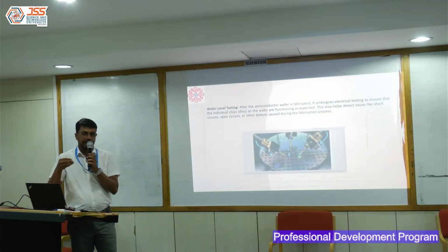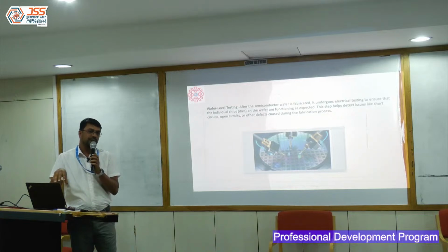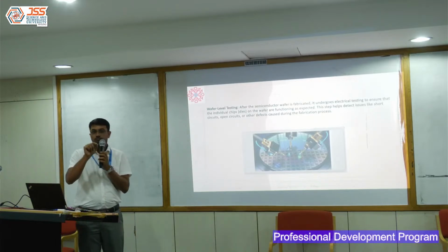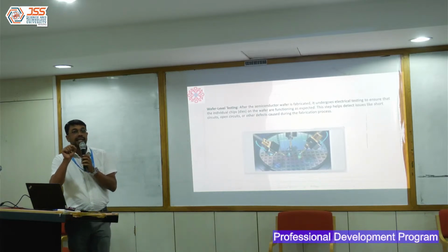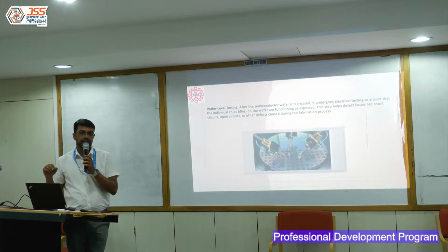When this technology started as a new technology, the yields were typically 20 to 30%. But they also learn from the first set of fabrications that they do. As I told you, I was talking about something called yield analysis. When I said yield is say 20%, out of 100 dies, 80 dies are rejected dies.